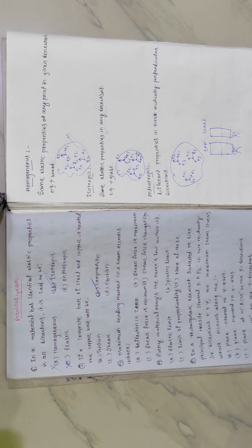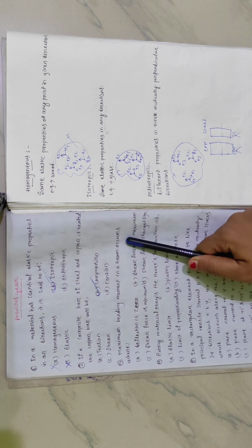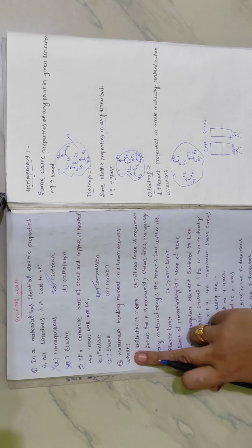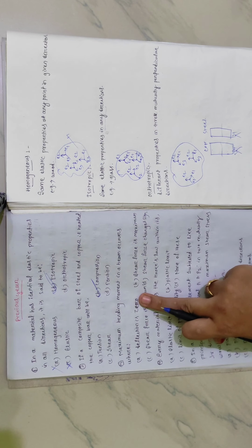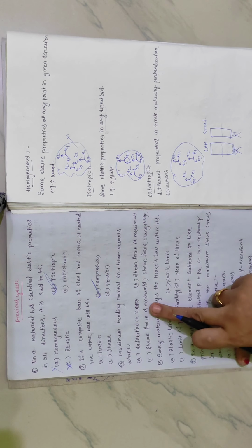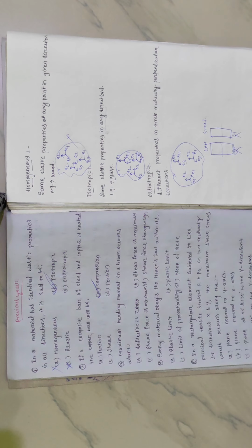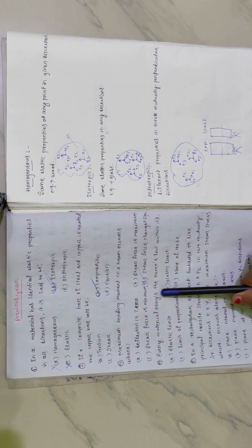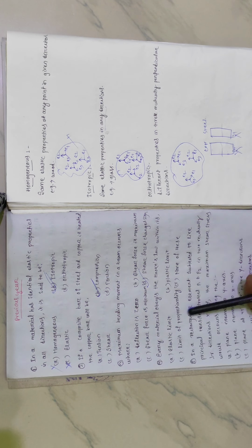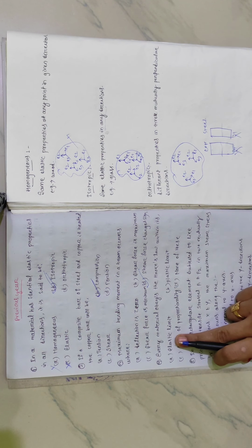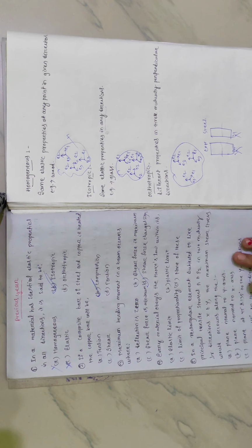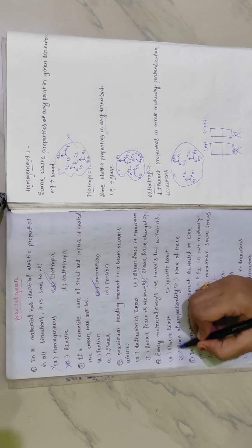Okay. Let's go to the third question. Maximum bending moment in a beam occurs where? Options are deflection is 0, shear force is maximum, shear force is minimum, shear force changes sign. So the answer should be shear force changes sign. Every material obeys Hooke's law within its: options are elastic limit, plastic limit, limit of proportionality, none of these. So this should be limit of proportionality.